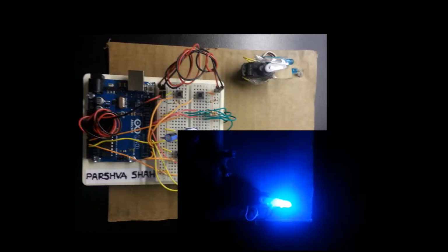Now, for the working of the system. The photo sensors need to be calibrated for the maximum and minimum lighting conditions. This calibration has already been done for the system. Being a basic system representation, the code used asks for calibration once every time the system is reset. The code allows 5 seconds for calibration.